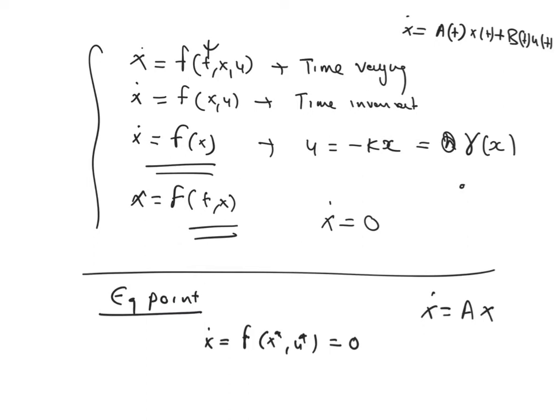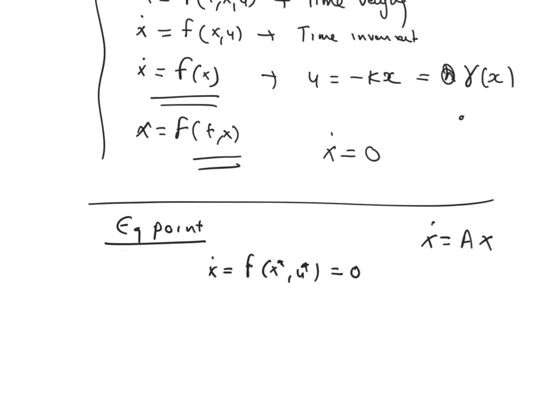It's so interesting: where you start, which point you start close to, you might converge to a different equilibrium point. In the nonlinear system, there was one equilibrium point here which is unstable, and one equilibrium point here which is stable. So stability is the property of the equilibrium point, and that is an important aspect. So it's very important to first find out what the equilibrium point is.